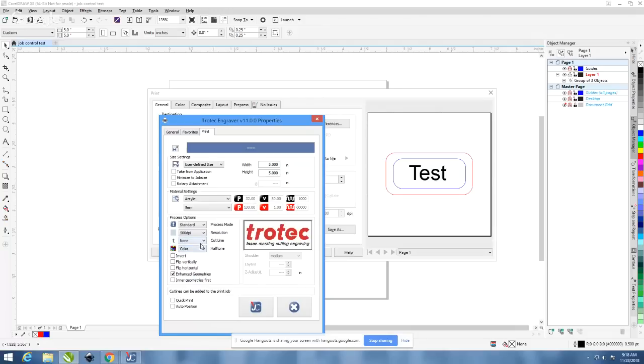Okay, so that's it for color. So moving on to black and white, this is great if you want to do a quick engraving of a logo, if the background is somewhat white. You can easily send in a bitmap and convert it to all black, and it'll engrave that bitmap or logo or what it may be. So this can save you time rather than having to drag a logo into CorelDRAW and having to vectorize it. You can try this method and hope that it works. If your photo's high enough resolution, you shouldn't have any problems. But again, if you have a low quality photo and there are some resolution issues on the edges of your shapes, it might not give you the quality that you're looking for.